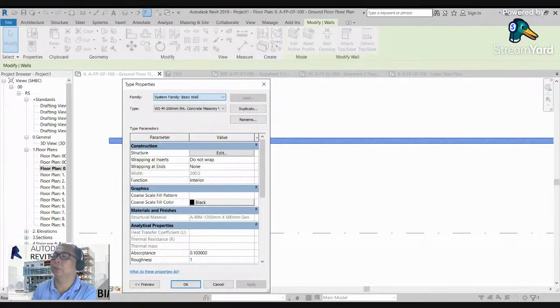So we will discuss what is the usage of these three types of walls. You can edit this. This is the type, which means the type of wall, whether this is CHB wall 100 or CHB wall 150, 200, or 300. You can create by duplicating the walls here. You can also create the gypsum wall, the board wall, or whatever types of wall cladding you can create here.